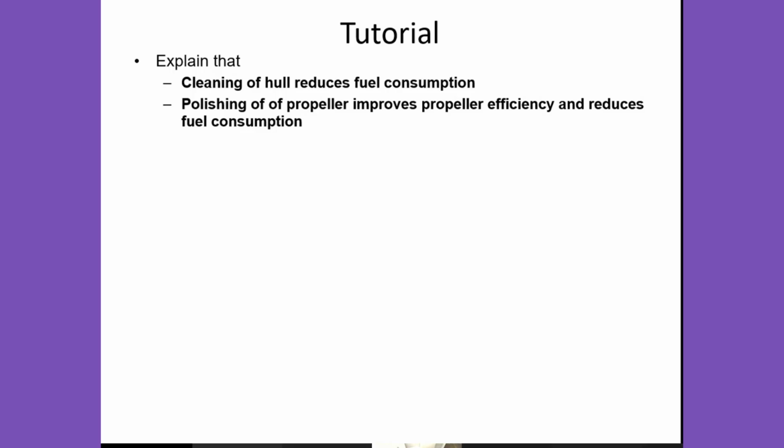So if the vessel is operating at high speed, we have to take care of the residual resistance more than anything else. And if we can reduce the residual resistance, we can obviously reduce the total resistance of the vessel. So the bulbous bow plays a role where high speed is involved, and there it reduces the residual resistance component of the total resistance. So the vessels without a bulbous bow will have more resistance, right, sir?